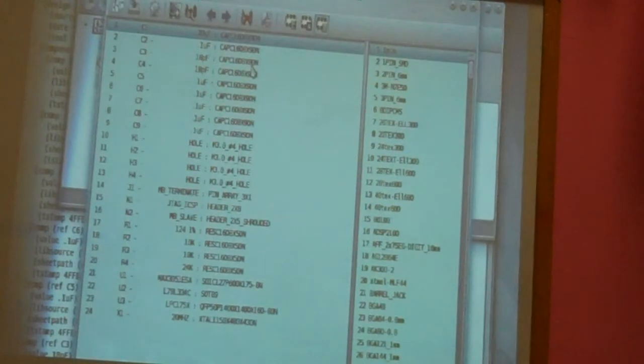The other thing is you'll see an X followed by a 90. The 90 is how high the component is. You say, footprints, who cares about height? You, as a PC board designer, could care less about height. If you're going to manufacture this thing, you need to know how high the part is so that the pick and place machine doesn't try and shove the part through the board. So it has to know the height. That's why the footprints have a height in them.